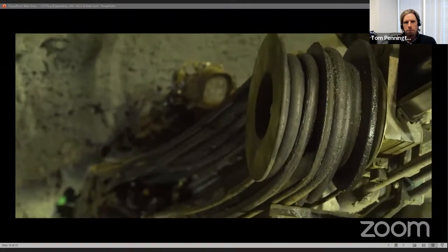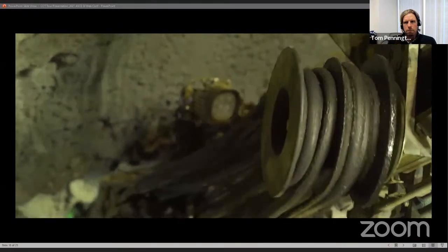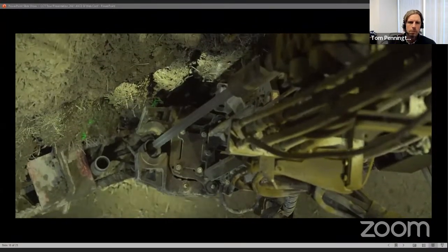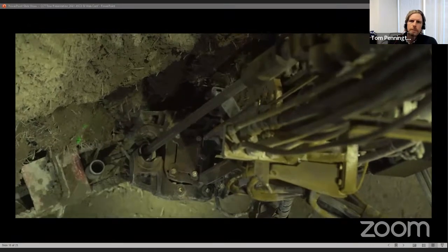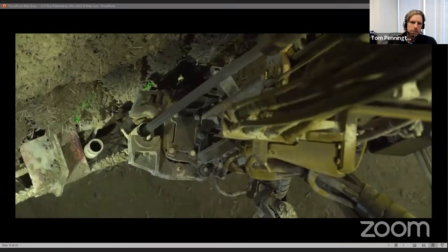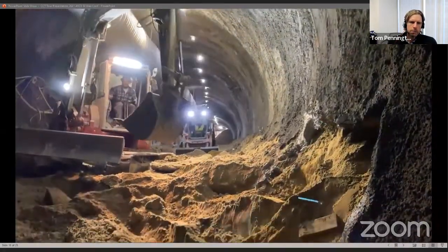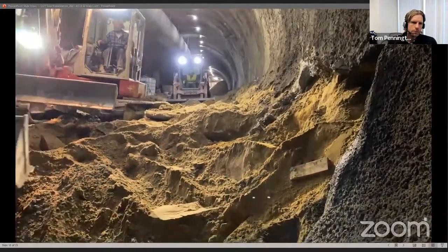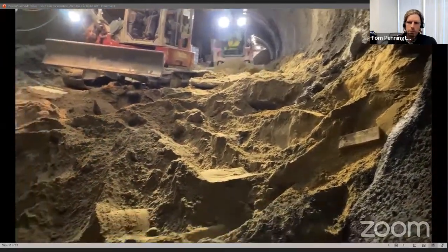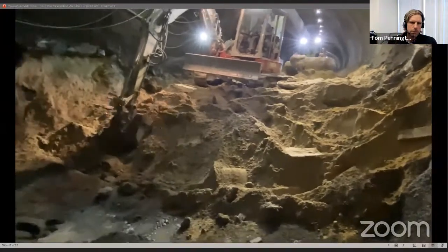Excavation on the remaining 131 feet of tunnel was carried out in the same fashion and sequence as before the alignment beneath the canopy pipe arrays. After the top heading is excavated to the full length of the tunnel, the crew will excavate the bottom half of the tunnel, known as the bench.